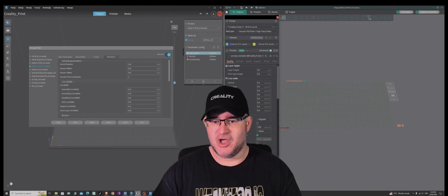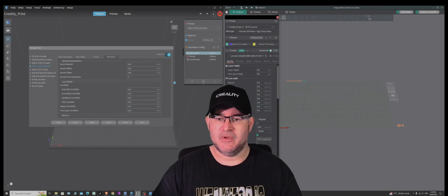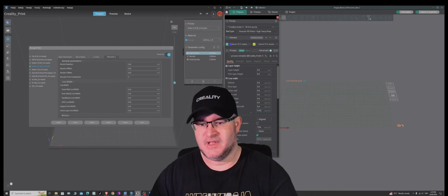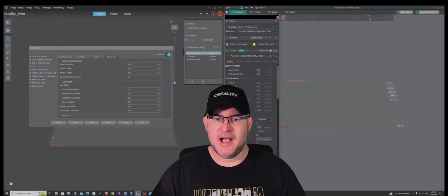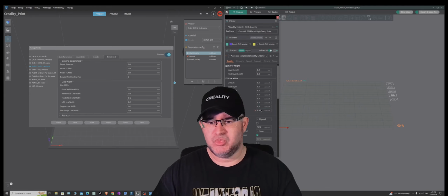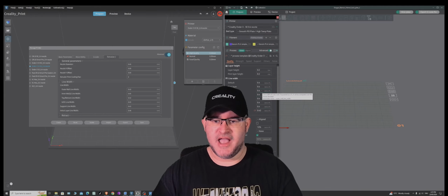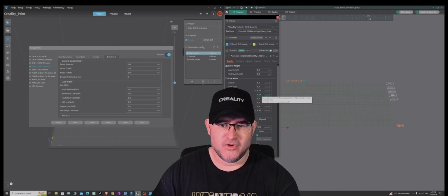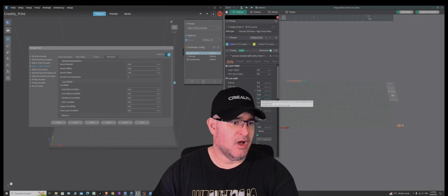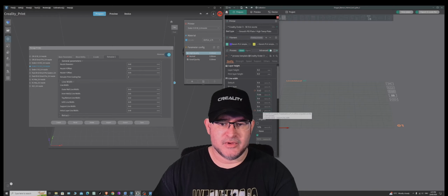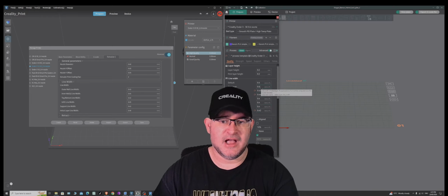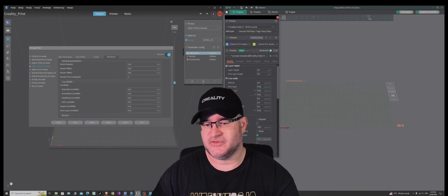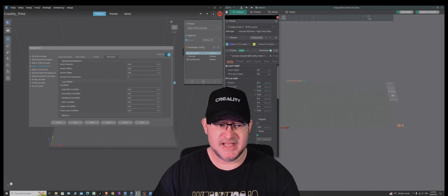So you can simply go along and, for instance, say support line width, it says 0.42, so we want to go with support line width 0.42. It's really that simple. Obviously, once you put these line widths in, so you've got your outer wall line width, for instance, is 0.42. Inner wall line width, what we've got is 0.45. Our top surface, what have we got? Initial first layer, they've got it written down as 0.46 for a slightly wider line, which gives you better bed adhesion.